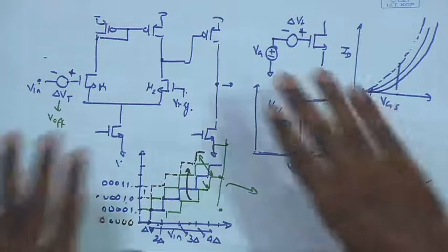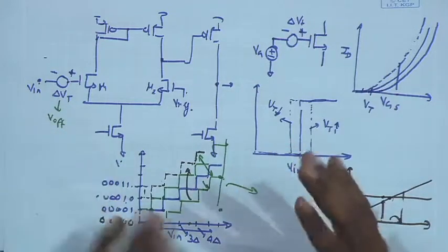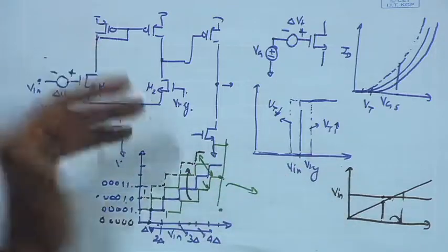And the more severe thing is, you are using two different comparators. For NMOS and PMOS, the shifts can be opposite, and in that case the mismatch effect is even worse. And another point is it can shift over time. So, there can be time dependent shift in Vt. There are some mechanisms through which we can have time dependent shift in Vt, like temperature. Temperature changes, Vt can change, and as a result the PMOS and NMOS have different temperature coefficients for the Vt, and that can lead to different shifts in the Vt.